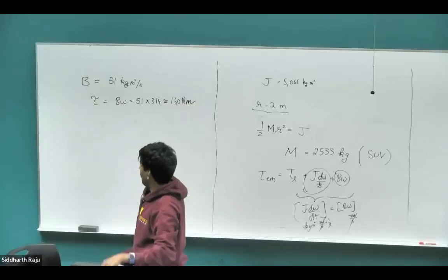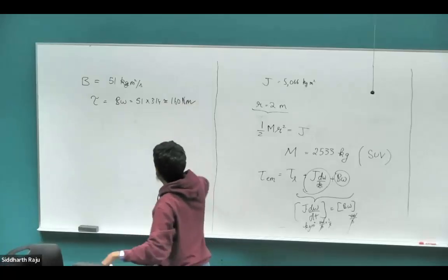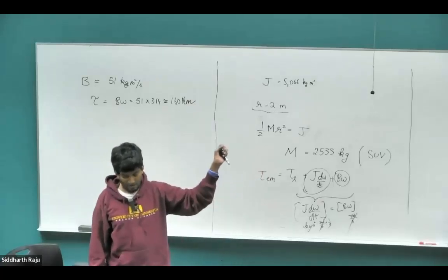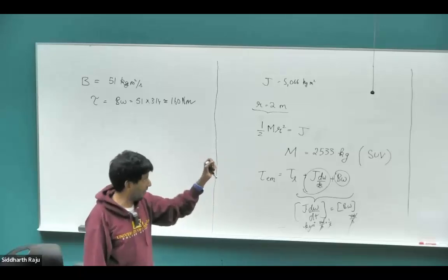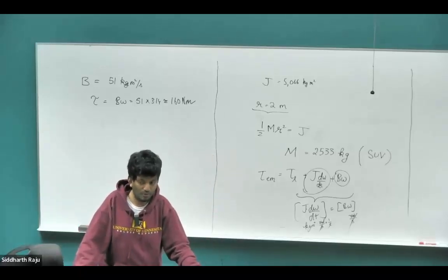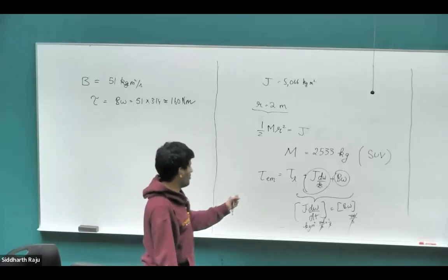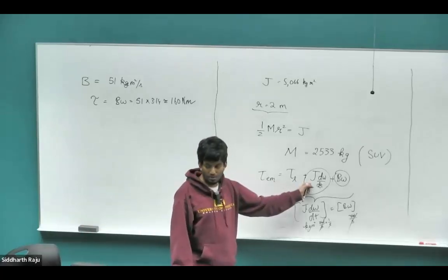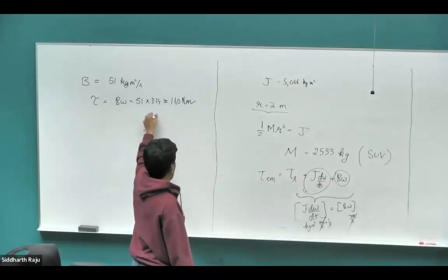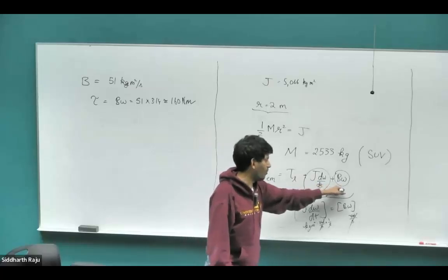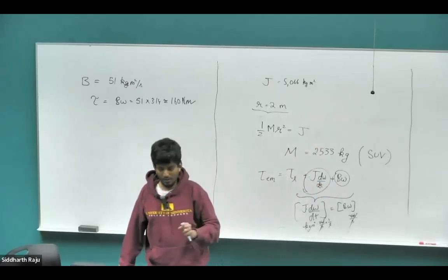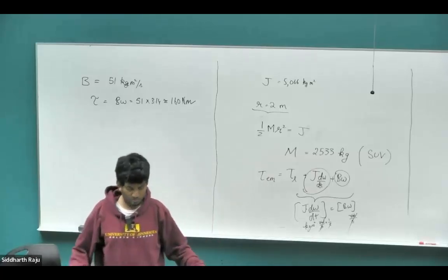Right? So in this case, we haven't considered the inertia of the fan in the attached rotor structure. Particularly for a fan of that big size, inertia would play a very big component that cannot be ignored. So our actual equation should have been tau m equal to J d omega by dt plus B omega. Just to make it extremely simple, we are only looking at B omega alone because we looked at J d omega by dt as a separate case when we looked at the energy stored in a flywheel and so on and so forth.